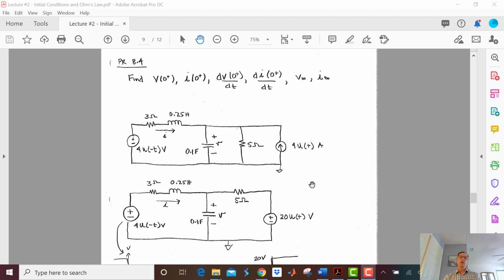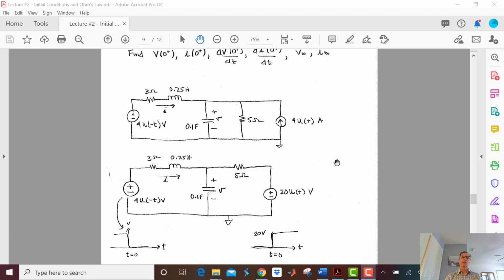Because the Thevenin equivalent might just make it easier to solve the problem. Similarly, if I see a voltage source in series with some Thevenin resistance or impedance, as we'll get into later in the course, I want to look at it as a Norton source because that may make the problem easier. So in this case, I'm going to take these 2 components and make them into a Thevenin source to make my problem look easier.